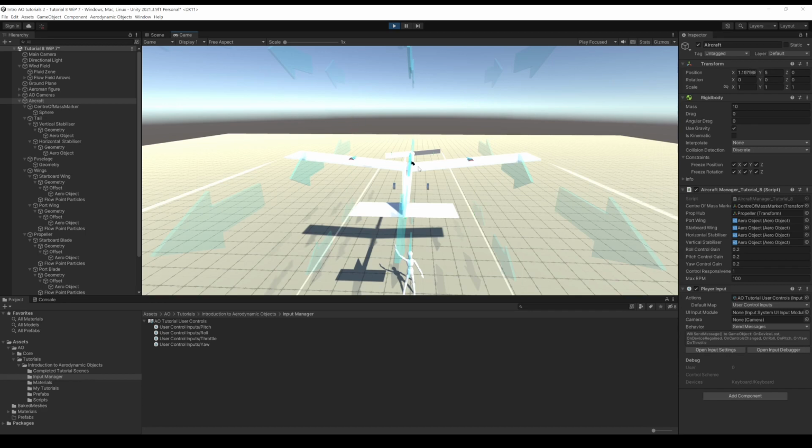So what's happening here, we've got wind blowing on our surfaces. As the aircraft stands there, it's not actually generating lift, but it's just a little bit of drag. But when we're changing the camber of the surface by doing the control inputs, that changes our aerodynamic forces. And that's the basis of how flight controls work. Whether it's flaps or anything else, what you're effectively doing is changing the camber of the surface.